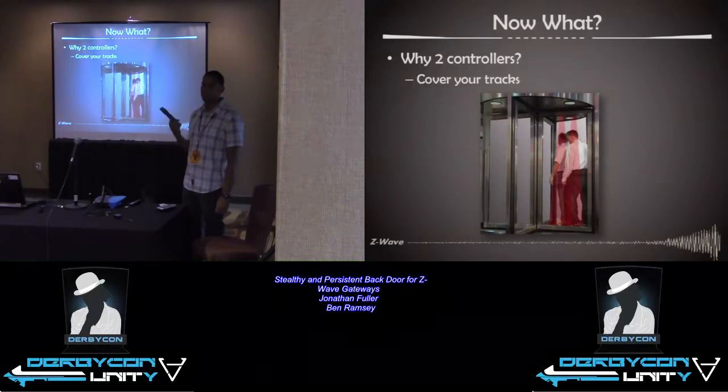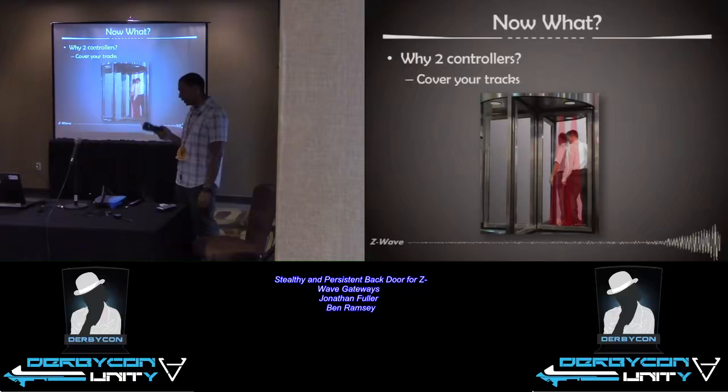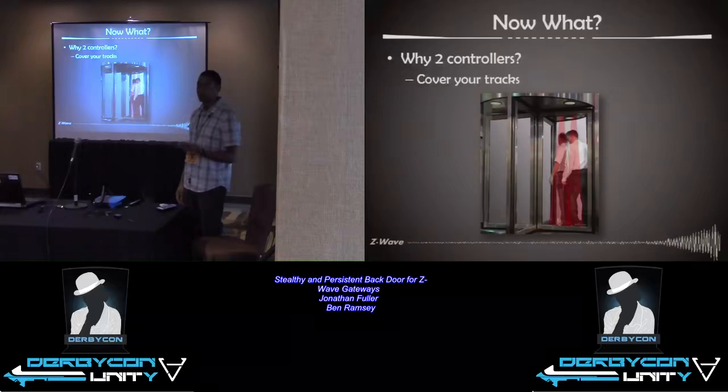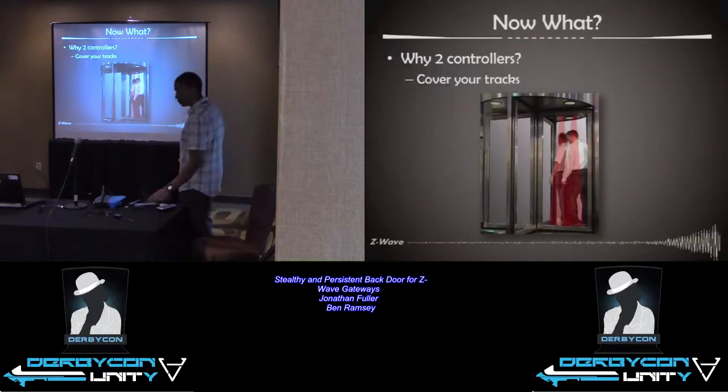You could still control the network from outside the home. And the cool thing about these portable controllers, the gateway, the homeowner has to have access to the gateway to actuate devices. So Wi-Fi in, Z-Wave out. This just communicates in the sub-gigahertz spectrum. So if you unplug the gateway or you take the gateway off the wireless local area network, this is at 908.4. It doesn't need the gateway to access the devices anymore. So you still maintain persistent access, a backdoor to the devices on the network.